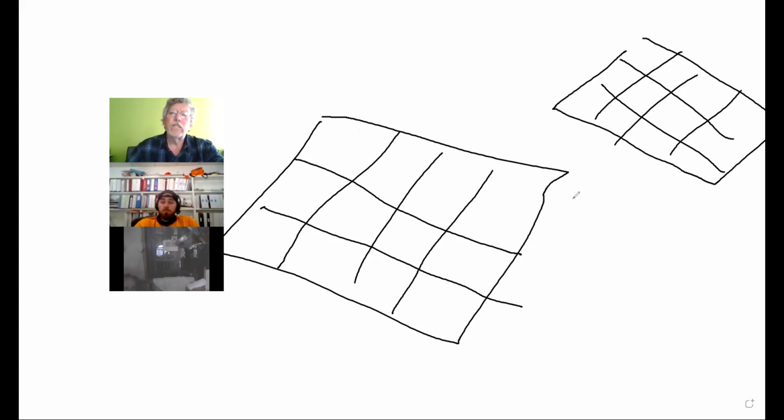Okay. Yeah, you answered the question. About three? Yeah, about three. And part of the reason is the rails usually come in 11-foot lengths. So if these rails are standardly 11 foot, three panels will fit on it without you having to special order a different rail. And that's a landscape three. Yeah, a landscape three, which again, for many of your systems, is fairly typical for a ground mounted system. Okay. All right.